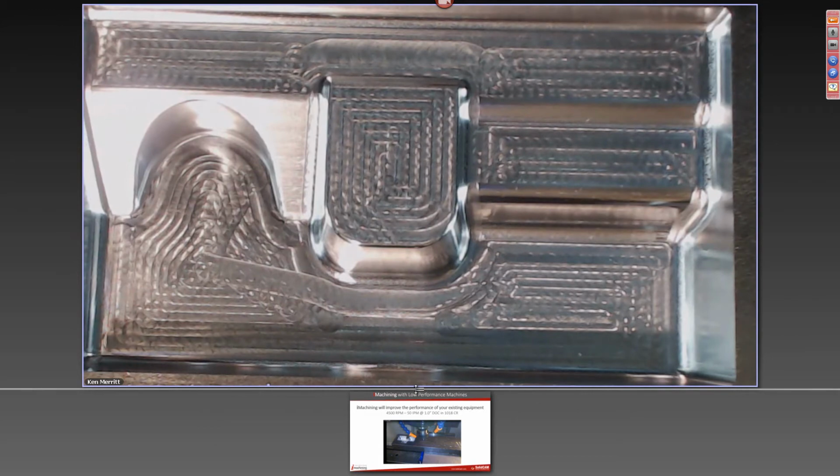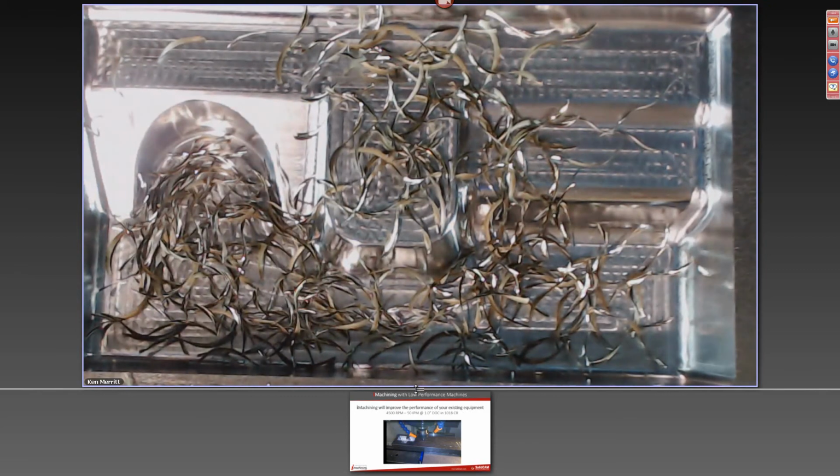Okay, so a couple things I want to talk about before we go into this video over there. Let me sprinkle just a few of these chips out here. One of the things we didn't really talk about while this was cutting, and it's one of the really important things, remember we were talking about cutting between a minimum and a maximum angle, all right? Well, most CAM systems today are calculating a chip load. Chip load is computed at the 90-degree quadrant as the thickness of the chip per flute, per revolution of the tool, straightforward advance. What we calculate is actually chip thickness. We're calculating that chip thickness at the cutting angle. So if at any given point through the algorithm, the tool is at, say, 47 degrees cutting angle, the chip thickness is actually being calculated at that angle.